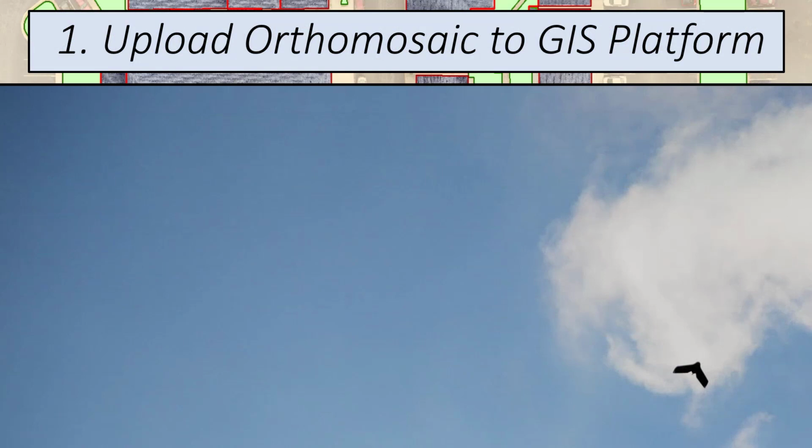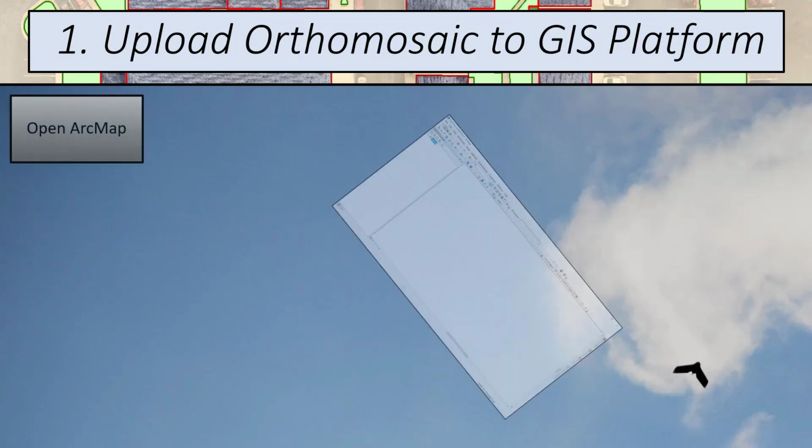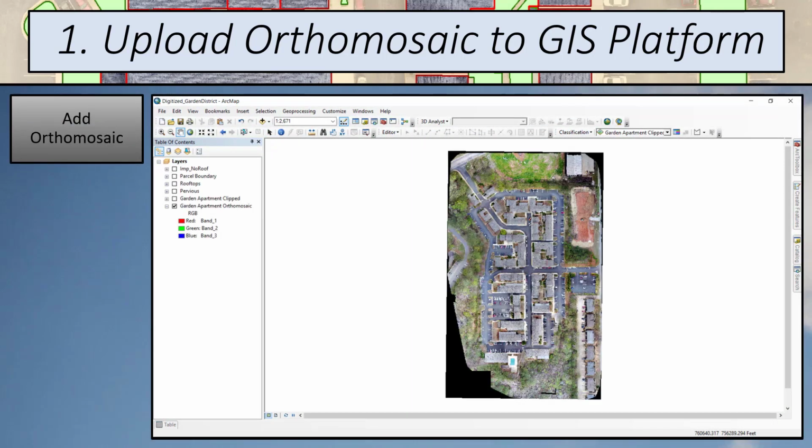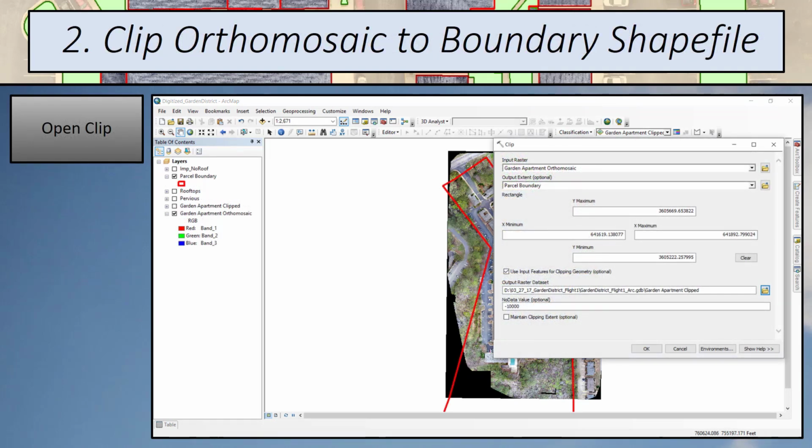So going back to step 1, we'll want to upload our Orthomosaic to our GIS platform. Therefore, we first need to open ArcMap. After we have it open, we'll want to add our Orthomosaic. With our Orthomosaic added, we can now get ready to clip it to our boundary file. For our boundary, we are using the parcel shapefile provided by the city government.